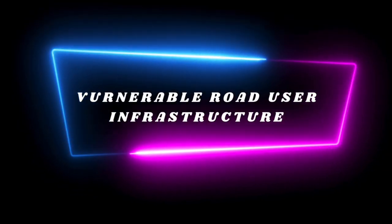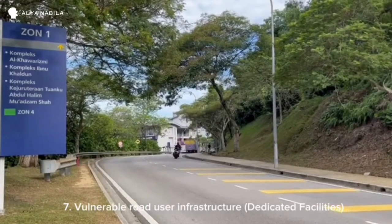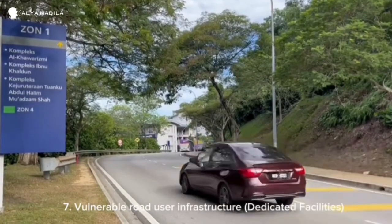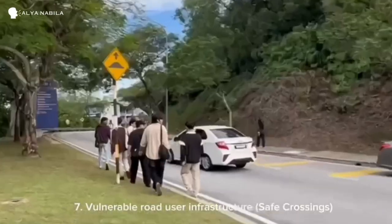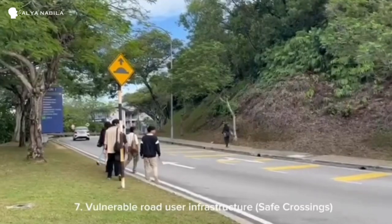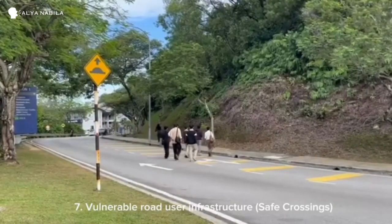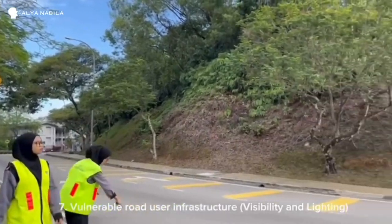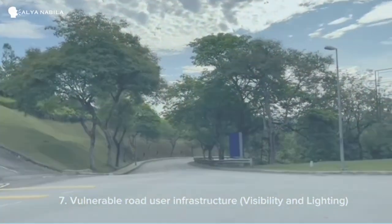Vulnerable road user infrastructure. Next, for vulnerable road users such as pedestrians and cyclists, the dedicated facilities show that the motorcycle lanes are not physically separated from vehicular lanes. For safe crossings, there is no zebra or pedestrian crossing at appropriate locations. Lastly, for lighting, poor lighting can reduce the visibility at night for the pedestrian and cyclist path, as the trees might block the lighting a bit.